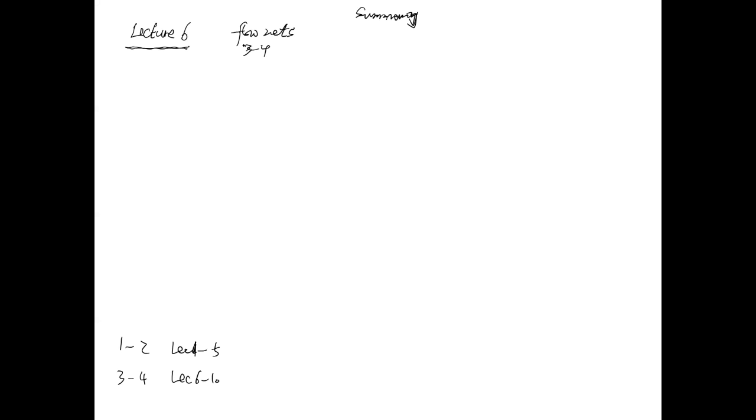And then one important part is, once you get the flow lines, you need to know how to get NF and ND, the number of flow tubes and also the number of head drops. Then according to this, you are able to work out the flow rate, or the seepage. Q equals K times NF divided by ND times the H. So you need to use this formula to work out the seepage.